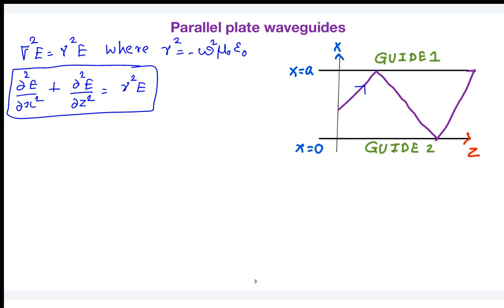And we know that when the wave propagates along the z-axis of the medium, it exponentially decays with the increase in distance. So let me generalize it. When you are generalizing the electric field in the z direction, you already know that for any type of wave, it has to exponentially decay with respect to distance. So let me call it E naught into e power minus gamma bar z. There is a difference between gamma bar and gamma you have to understand.